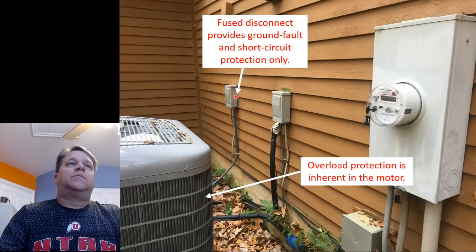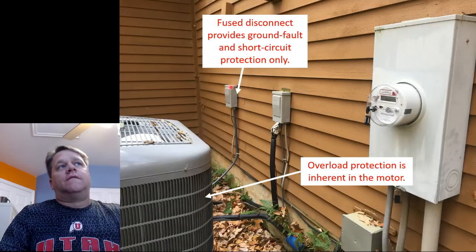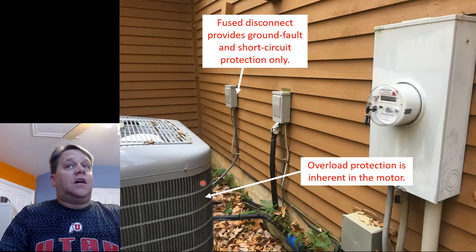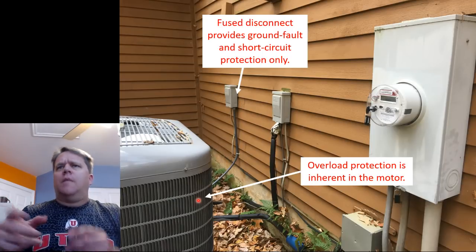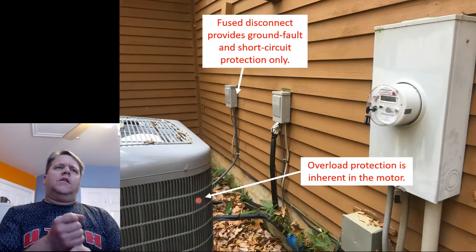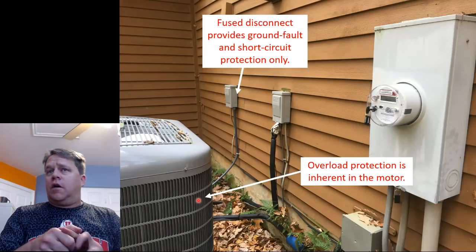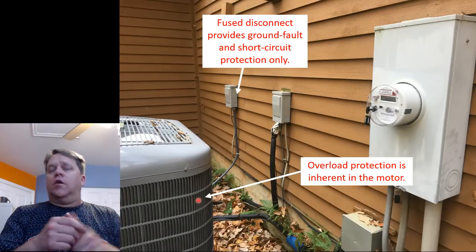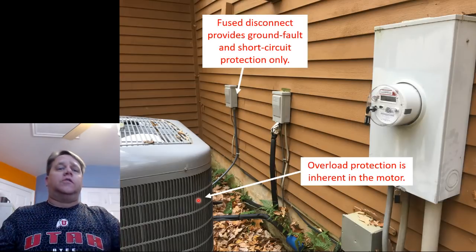This does not provide protection from all three. It only provides protection from ground faults and short circuits. We let the motor itself provide the overload protection. Now that's a little bit unusual. If we think of a bathroom, for example, a bathroom's a nice easy circuit, right? 20 amp circuit. The 20 amp breaker for a bathroom provides protection against overloads, ground faults, and short circuits, right? Overloads, again, if I take 5 hair dryers and 3 curling irons and plug them in, that's an overload. The 20 amp breaker trips.